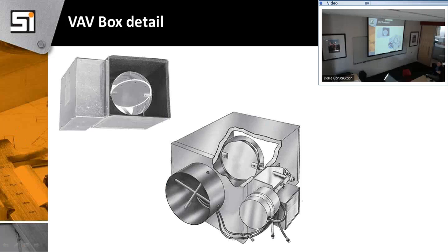This is just the VAV box we were talking about. Basically, we have an actuator, a flow measure, and a damper. We like to keep some straight entrance into this so we get good flow measurement. But at times you almost have to crank it in there, and they put a correction factor on that. But VAV box, who supplies the actuator? You?